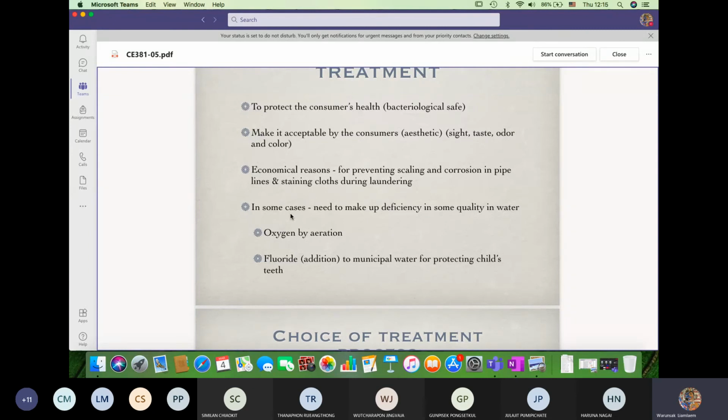But the problem with the boiler is that it is the equipment we use to convert water in the liquid state to vapor. If we boil the water, of course we get steam. But if we boil hard water, what will happen? Once we boil, some of the calcium and magnesium will be precipitated, or we can say that the hardness will be removed, because it is all temporary hardness, not permanent hardness. So once we boil, it becomes precipitated forms. If it precipitates in the tubes in the boilers, at some point the tube scaling gets stuck, gets clogged, and finally it causes damage. Boilers cannot function.